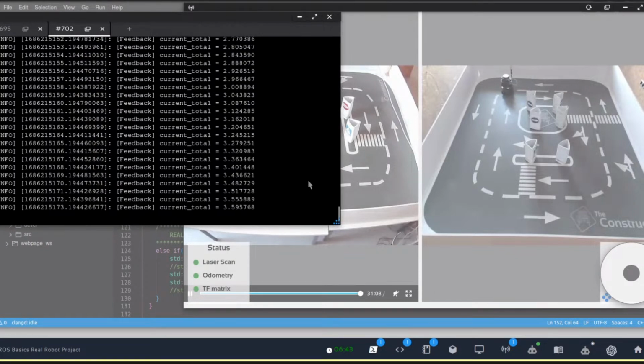So this behavior is a simple one. I implemented if conditions comparing in priority if we have a frontal obstacle with the front distance. If this condition is okay, that means that we don't have an obstacle. We keep going to compare if we're closer or further from the right wall. So it's a series of 3 if conditions. For the purposes of this project, I decided to keep it like that in order to go further with the main goal, which is to create this ROS architecture with services and actions.